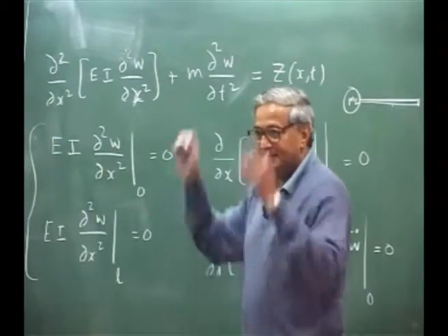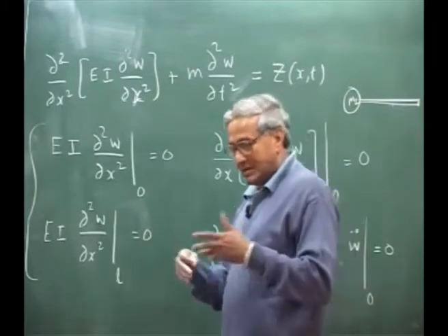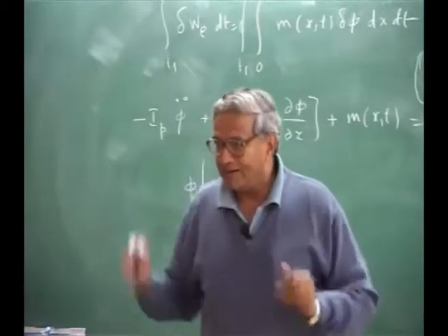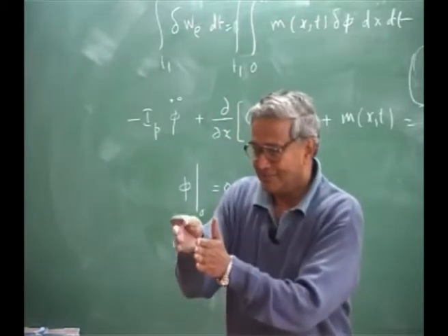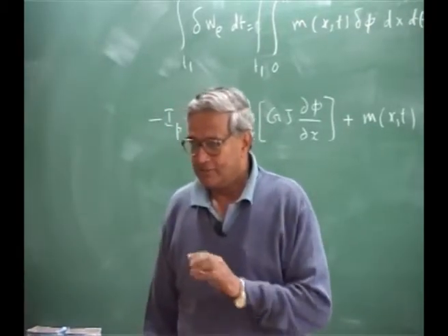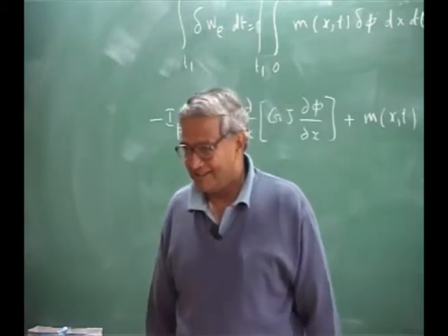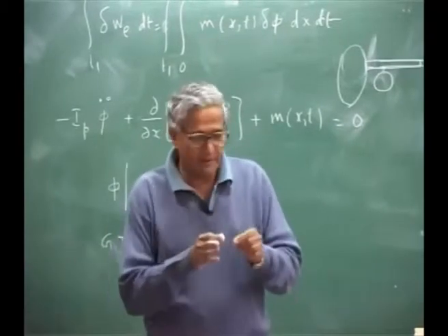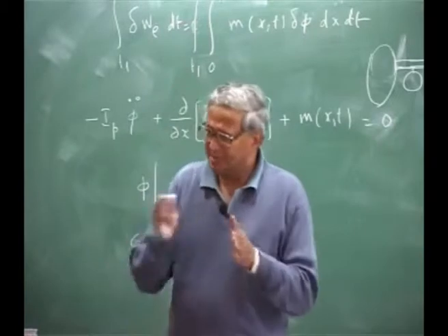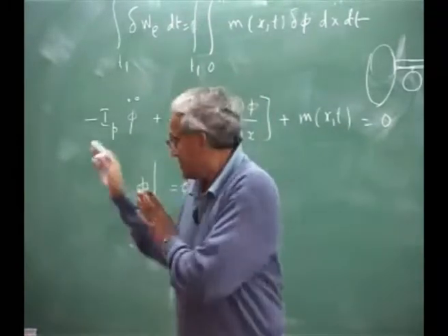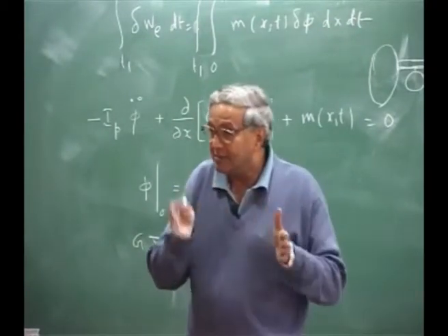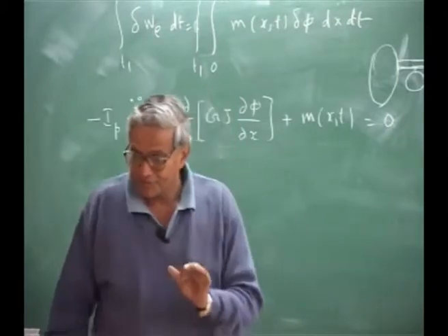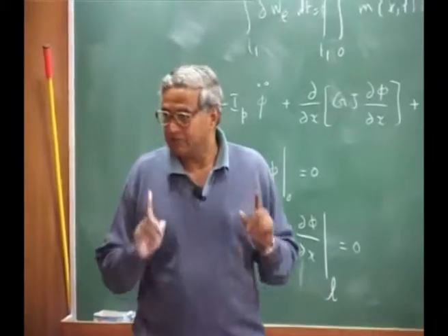What happens is at that location suddenly the mass changes. So either you can put it like a delta function into that whole problem, or you may have to split the beam into two parts, okay, then put that mass at one end, and at the other end you start as a free end. So the problem gets a little complicated. You can't solve that so easily, depending on what you put where. Now this is where you learn the approximate methods, because you cannot get a closed form solution. Suppose you have a beam which is supported at several locations, that is multiple supports. You can apply these equations piecewise, substitute the suitable boundary condition at every point. Okay, that is where the problem is very, very important: how you formulate your entire equation of motion and the boundary condition.